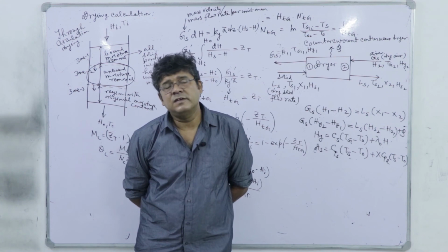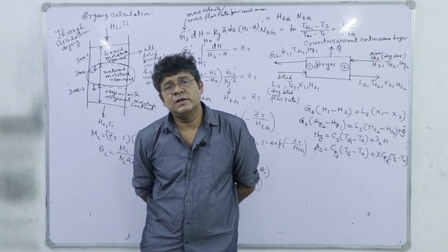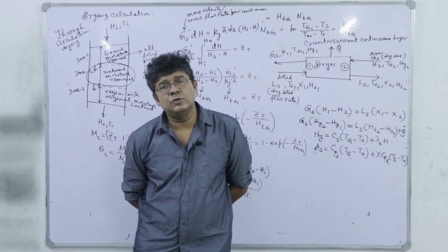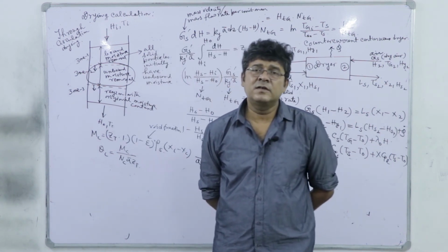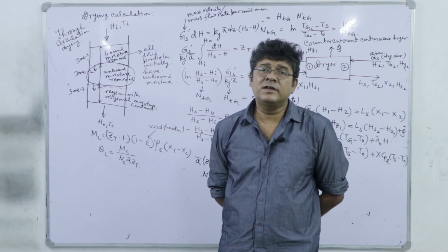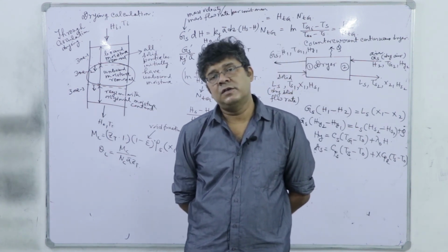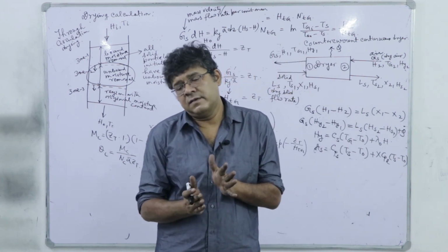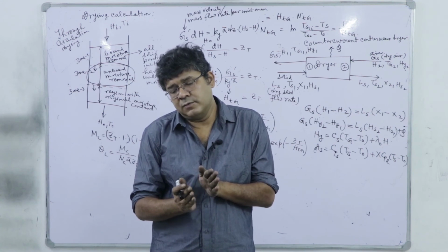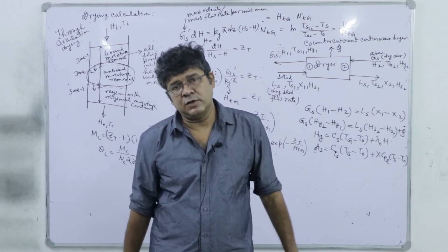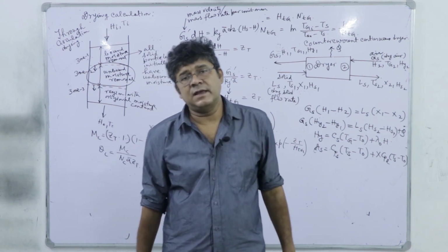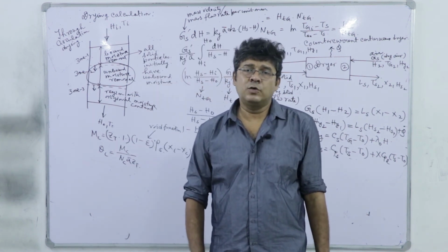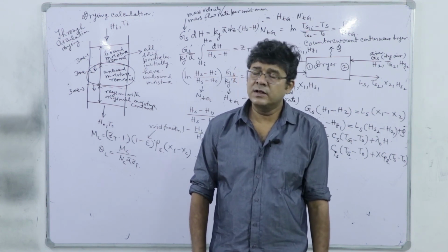But we have seen that zone 1 will proceed or penetrate into zone 2, whereas zone 2 will penetrate into zone 3, right. It's pretty obvious, but note that the zone boundaries are not sharp, they are diffuse. So in that case the unbound moisture removal zone will finally occupy the zone 3, and in the latter stage zone 1 will occupy this entire area of the zone 2 or volume of the zone 2, right.